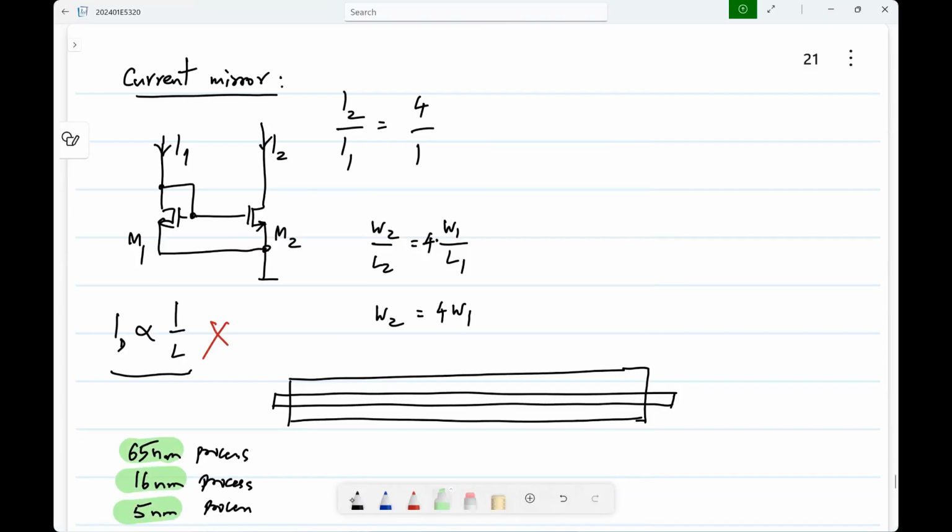Okay. It is either the minimum gate length or related to how closely two metals can be placed to each other, the metal pitch. Okay. So it is in a way a measure of how small you can make your dimensions on the IC. So the minimum gate length will be restricted to something. In a 65 nanometer process, it is 60 nanometers or something like that. But for width, there is no such restriction. Okay, that is, it depends on the amount of current you want to have.